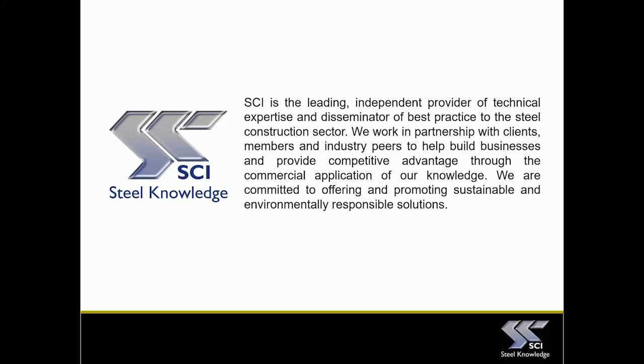So yes, you need to look at the different stiffnesses of those stability systems and distribute loads in proportion to their stiffness. That was one of the later slides that I had in the presentation.